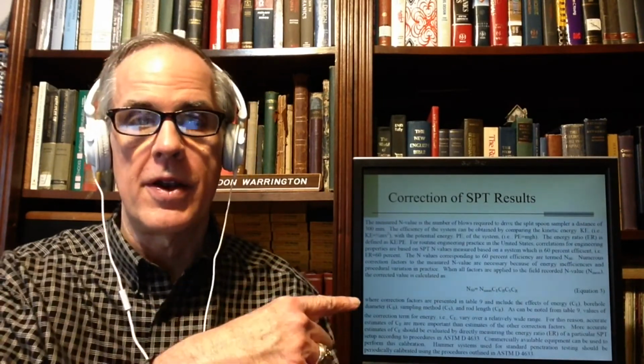You've got N measured there in equation 3 on the slides, which is the blow count you actually measure. And you correct it for 4 things. I'll talk about CE last. The other 3 are not as important. Therefore, borehole diameter, sampling method, and rod length.